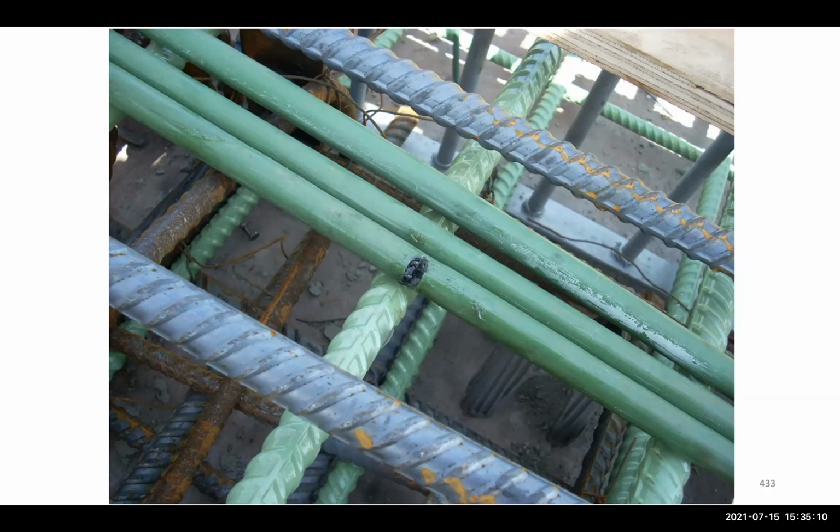If we have something like that, what does that mean? When we design and check stresses, just like we said in part one, we have to be accurate because concrete stresses may be exceeded. And we calculate that based on the PT force, whatever force is applied. So here you have maybe one strand. This is a 7-wire strand, right?